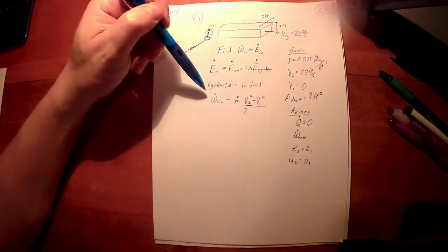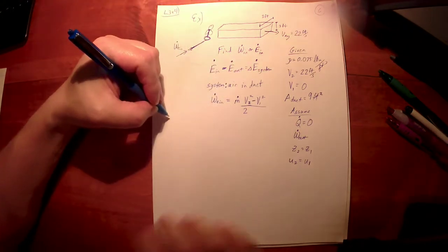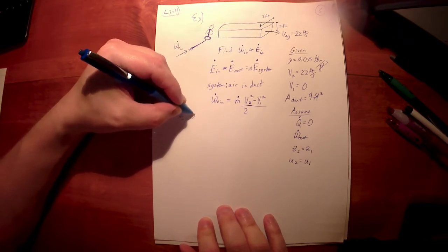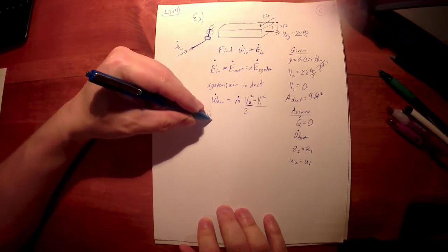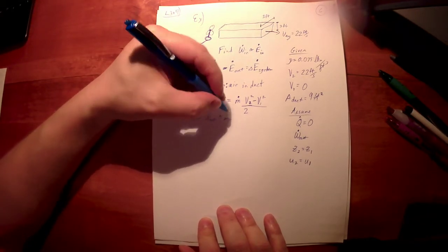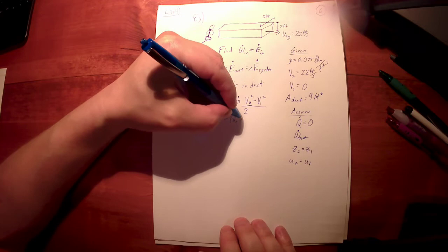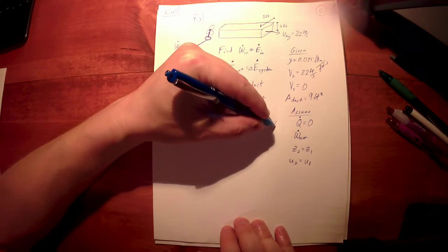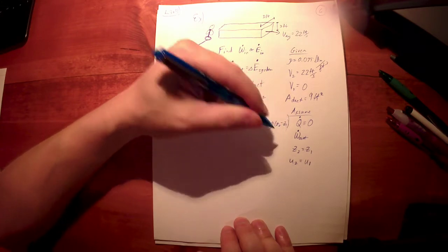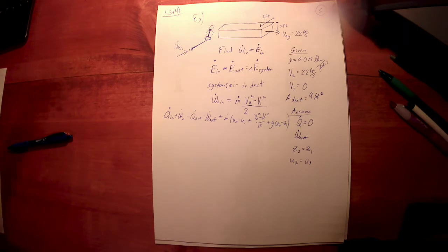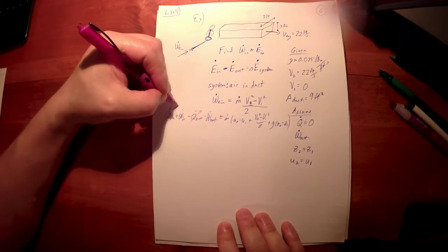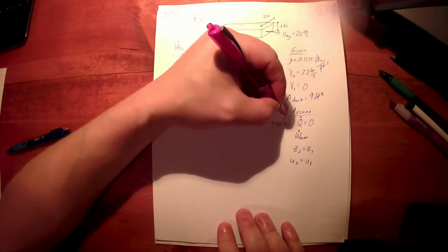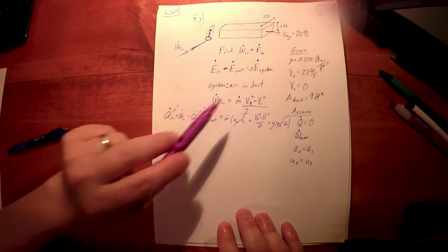We've made assumptions to simplify the first law equation, which, you could write this whole thing out and say, well, this is Q dot in plus the power in minus Q dot out minus the power out is equal to m dot times (u2 minus u1 plus (V2 squared minus V1 squared) over 2 plus g(z2 minus z1)). You can write the whole thing out. That's okay. All right, and then say, all right, well, we're going to have to assume those are 0, and assume this one's 0, and this is 0, and this is 0, and that's all that's left, and then you write this down.